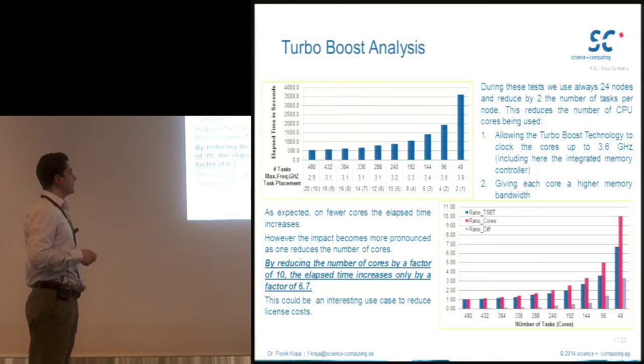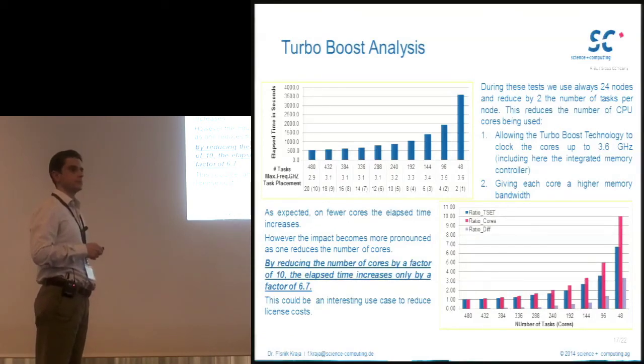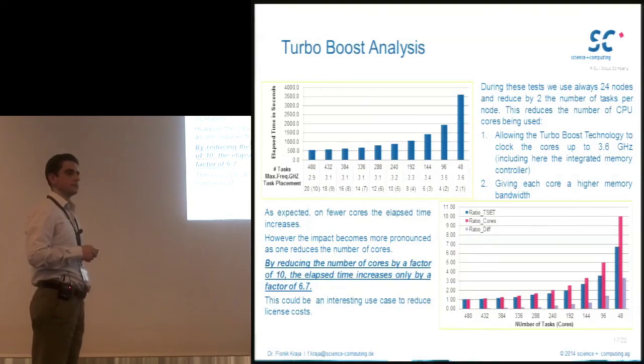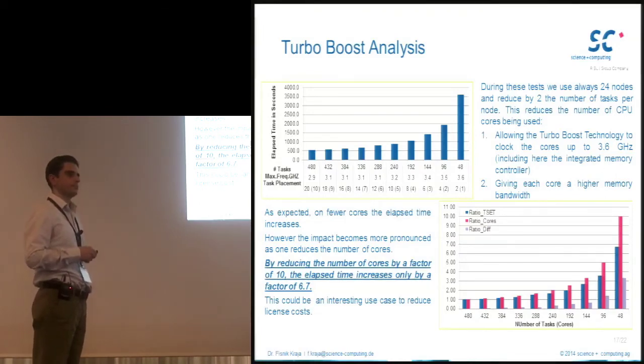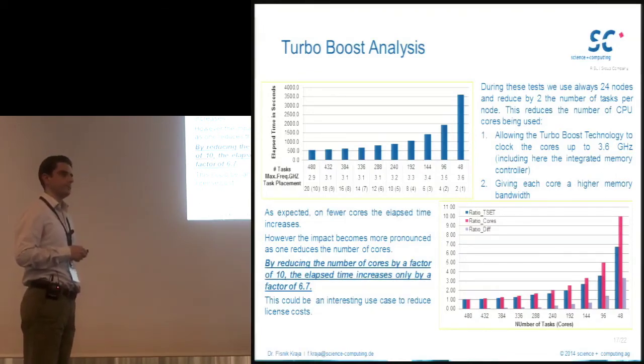And it's interesting you see the change in the frequency. We really measure the frequency. That's a known thing: you don't have control over the frequency when you have the two sockets active. If you run one core, you will have a frequency different than if you run all the cores or half of them, and the reason is just cooling. There are special cases, in Intel Sandy Bridge and Ivy Bridge, where you could cool it in a way that you reduce the frequency on all cores, but that's only in certain cases.